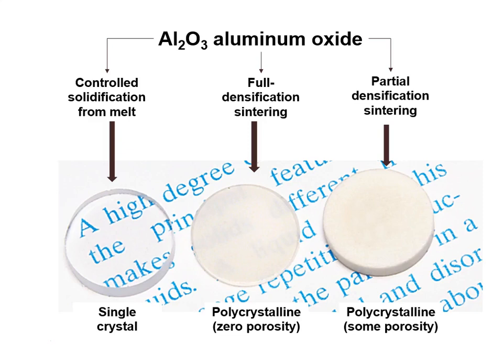As a fairly brittle ceramic, aluminum oxide is processed by what we call a powder metallurgy type of processing. You start with a submicron, fairly pure powder and subject it to high heat and pressure, and the need to reduce the energy associated with the surfaces of that powder will drive what's called sintering densification. The powder will actually fuse, form necks, and eventually the voids between the particles will be driven out, and you can obtain a fully dense structure.